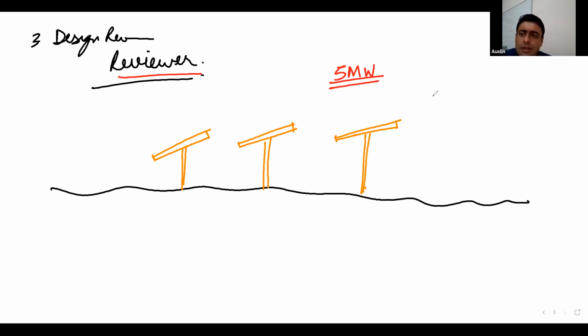In these projects, to save cost, we generally go for pilings, and those pilings are very short piles. Typically those piles would be around 1.5 meter depth, a single pile for one column.